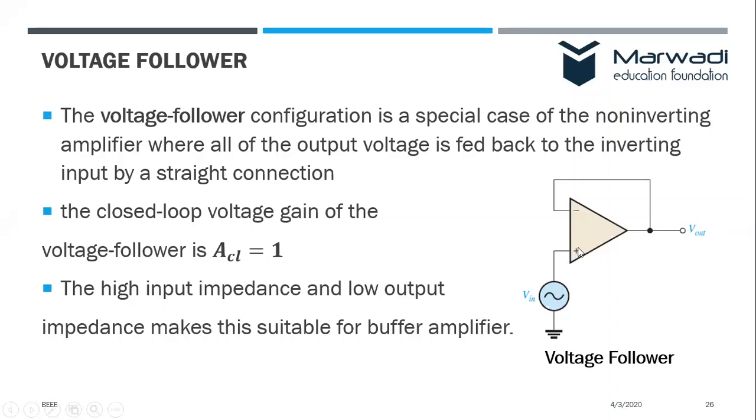The operational amplifier has a very high input impedance, so the weak signal is driving a very high input impedance. The current requirement from the signal will be almost 0. If the current is nearly 0, then the power required will be 0, so there will be no burden on the input signal, right?